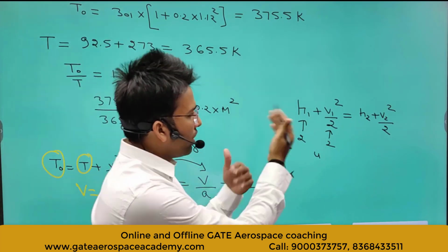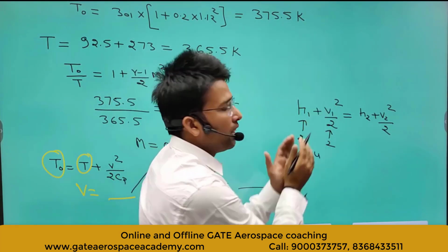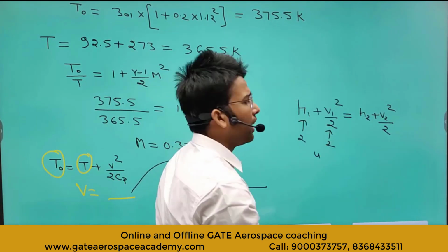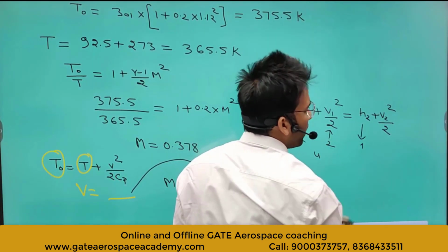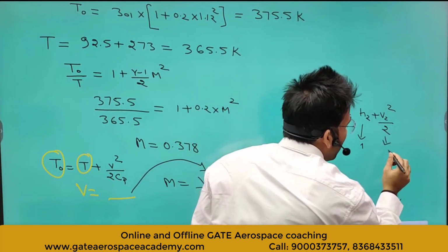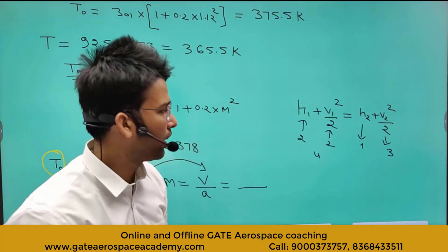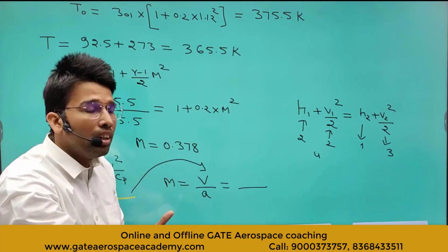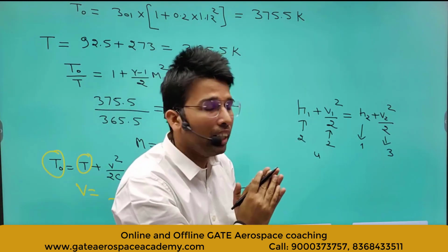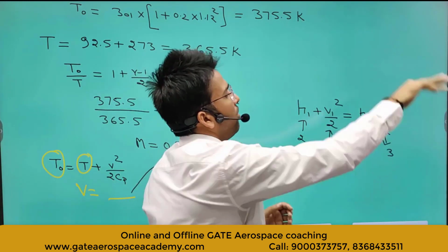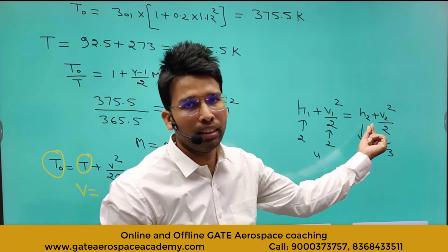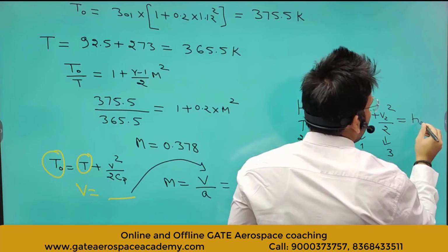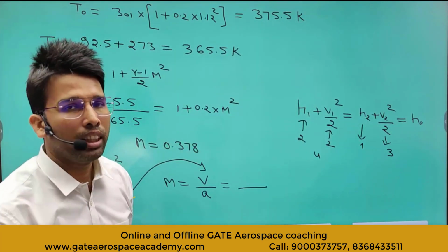So whatever happens with the flow, the summation of this energy will be constant, right? So let's say temperature is decreasing. So now this became 1 unit. So obviously this will be 3 units, such that the total will be constant. Similarly, at the stagnation state, again it will be 4 units only, right? Velocity will be completely 0. The entire thing will go into this enthalpy. Then we will write that equal to H naught, the stagnation state, right?